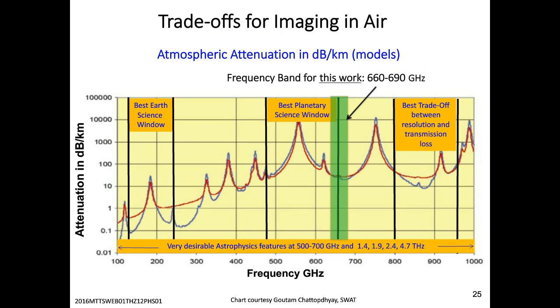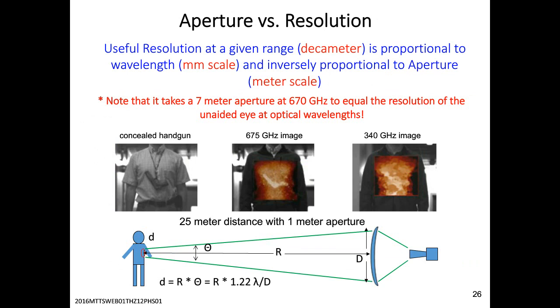If you work in an atmospheric window, like I show here on this slide at 670 gigahertz, you can do some things with active imaging and radar reconstruction that allow you to get object recognition with much better identification than you can do either with passive or with active imaging without the third dimension radar gives you, which is depth.